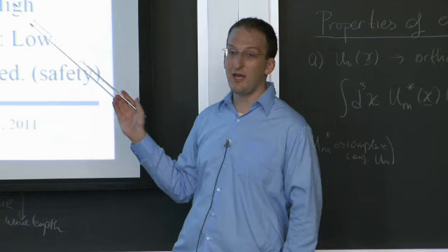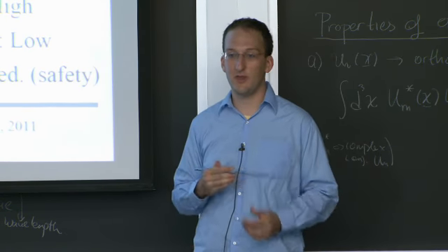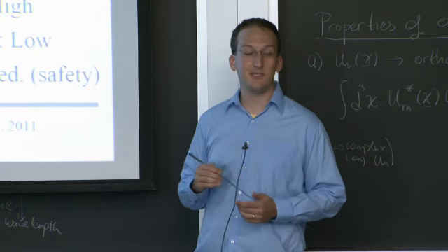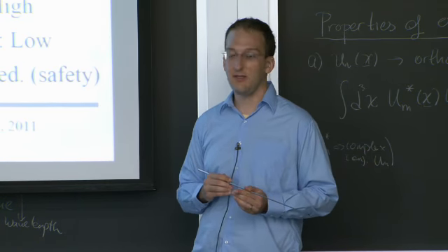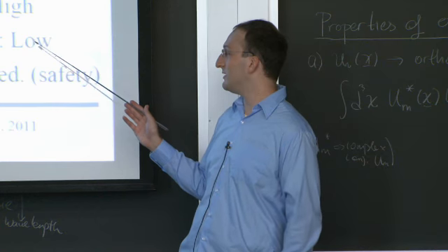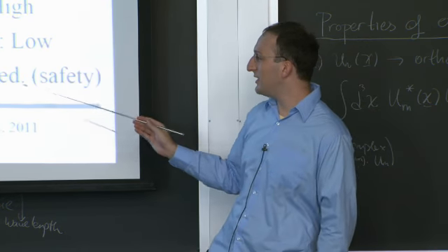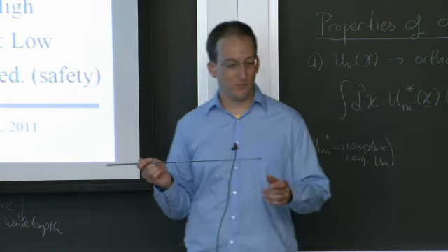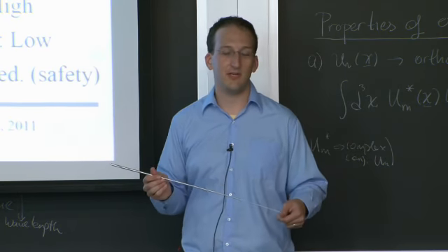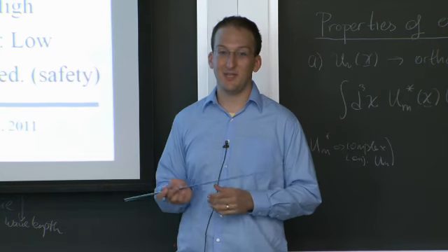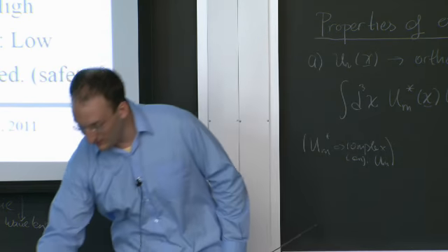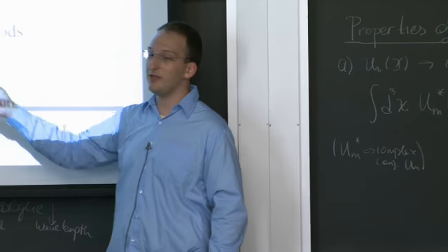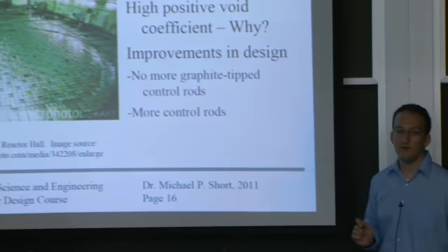They can be pretty high power. We're talking 4 digits up in the 1,500 megawatt electric design. There are still some of them running, actually. They have a fairly low power density. And I say the feasibility is medium because it's been done, but there are safety concerns. And you will probably have a hard time convincing anyone in this country, let's build RBMKs, because there's that stigma with them. This is actually a photo of the reactor hall in Chernobyl 3, one of the units that did not have the accident.